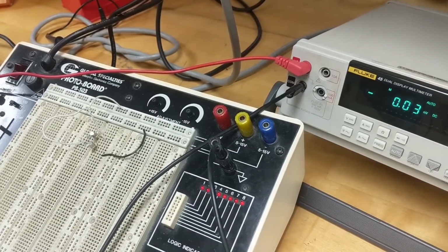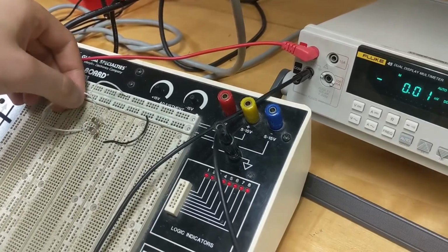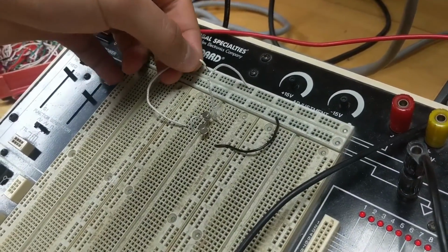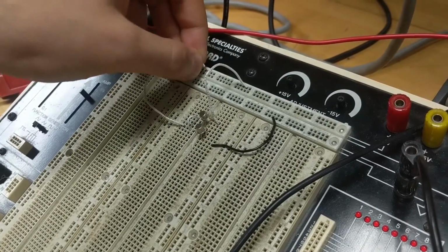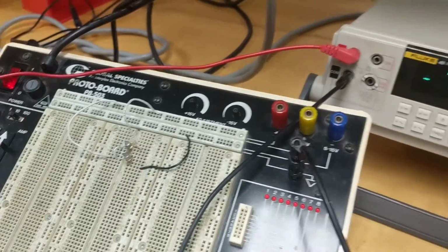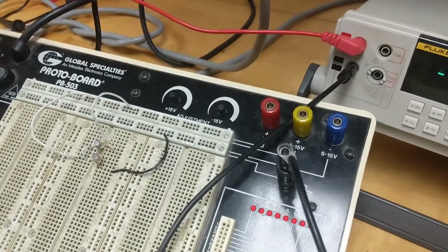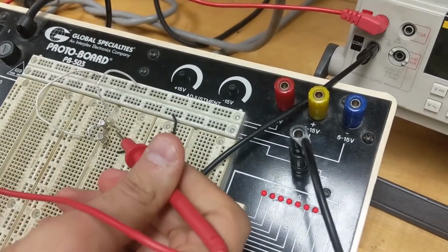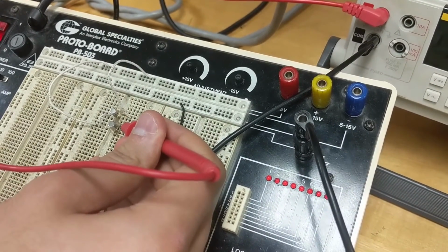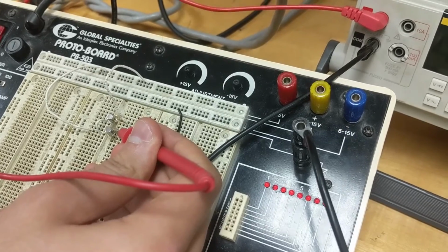Of course, the first adjustment will be to fix the input voltage to be of the DC supply of 5 volts. So we'll remove it from the ground, connect it to the DC supply. So this is the first adjustment to our circuit. Now we will apply the DC supply, and this is the case of RL equals open circuit, and we can measure V output between this point and the ground. So if we measure it, we can see that it's equal to 0 volts.